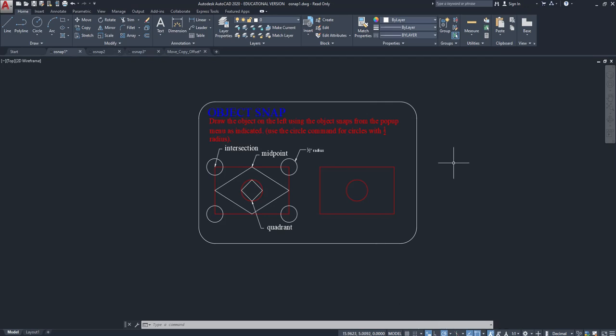But anyway. All right, so our object snaps, if you come down here to our object snap toolbar, it's down here in the bottom right hand of our screen, you'll see we have a bunch of different buttons, okay? And if the button is blue, like this one right here, dynamic mode, that means it's turned on, okay? So dynamic mode, we know what that is. This is dynamic mode, when you have all that input at your cursor, okay? If I click on it, it turns off. It grays out and it's turned off, all right? So now when I draw something, I don't see all that dynamic input, okay? So that's the first thing.